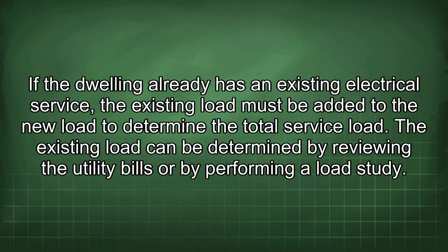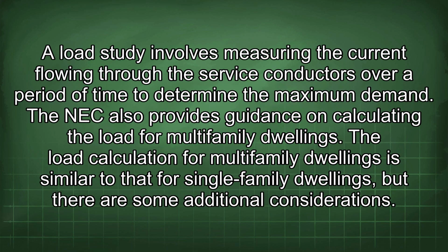If the dwelling already has an existing electrical service, the existing load must be added to the new load to determine the total service load. The existing load can be determined by reviewing the utility bills or by performing a load study. A load study involves measuring the current flowing through the service conductors over a period of time to determine the maximum demand. The NEC also provides guidance on calculating the load for multifamily dwellings.